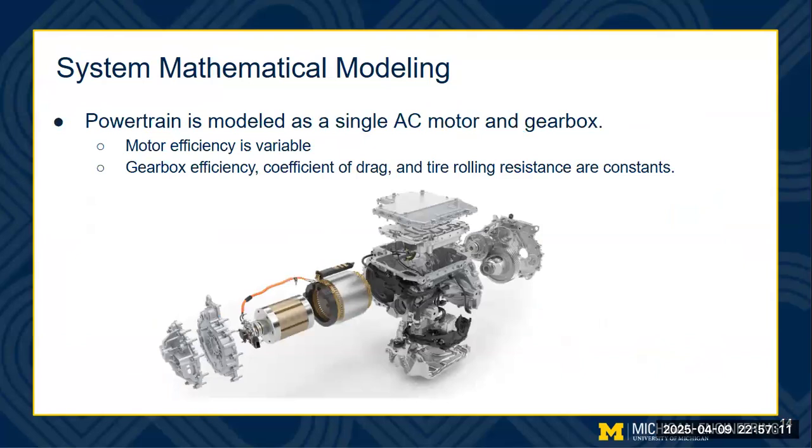The powertrain is modeled as a single AC electric motor and a gearbox with a drive cycle that governs the motor power demand. Energy loss coefficients are used for the gearbox, aerodynamics, and rolling resistance.